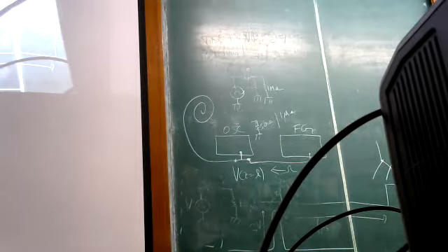So since this is a pulse, this should drop back to 0, and the pulse will traverse the whole length of the cable and then come back. So it should again be, I guess, 1 volt. Okay, I'm changing my answer here. Since this is not a steady state, the pulse goes, we see 1 volt, then the pulse comes back, we see again 1 volt. Did you guys follow that argument? Any thoughts on that?